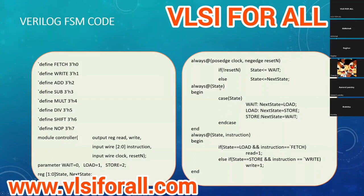Depending upon the state variable, the next state transition of the FSM will be from wait to load, load to store, and store to wait. So it's a cyclic transition. Then, based on the instruction, which is the input variable, if the state is load and the instruction is fetch, read will be 1. And if the state is store and the instruction is write, write will be 1. See the intent here. We haven't used 0 1 1 0. Now it's so easy to understand. If the instruction is fetch, read will be 1.